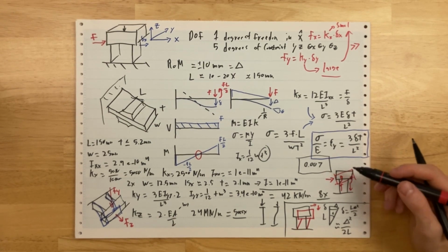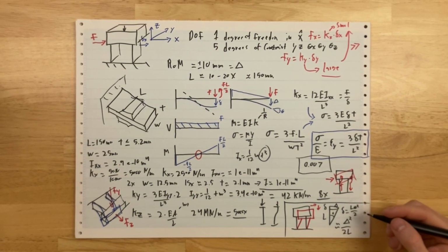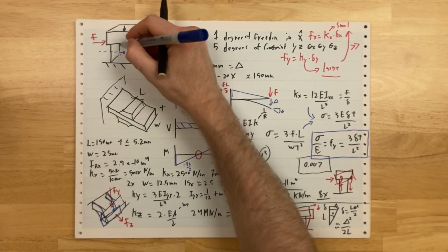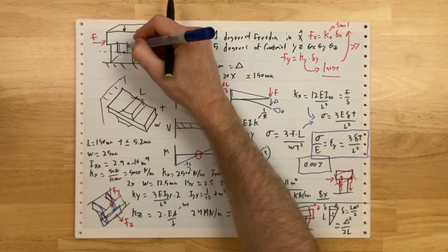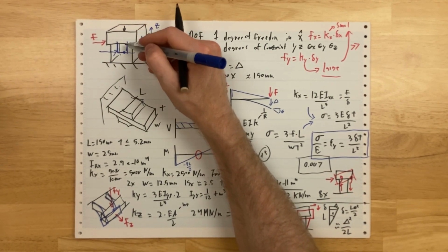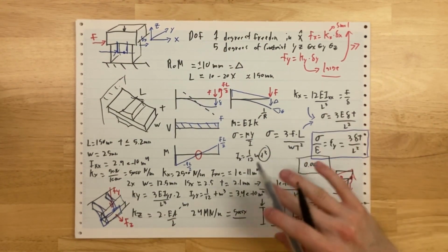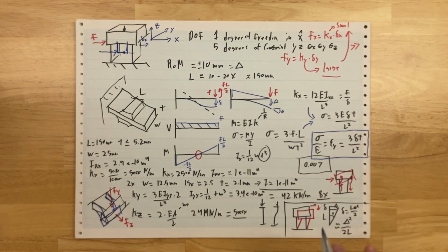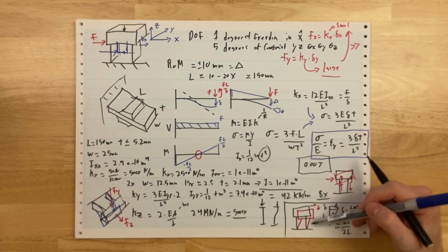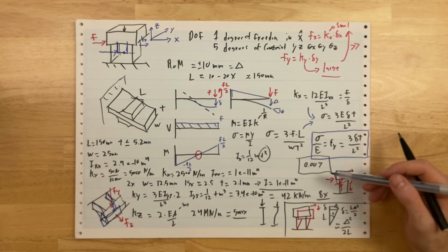If you work through the math, you'll find that the parasitic moment is FL/2. So what you can do there is if you push at the halfway point right here, let's say you build a bar that comes down from there, and you push at the halfway point, you can now add another torque that's FL/2 in the other direction. And that means that in static positioning, when you're moving really slowly, all the forces and torques balance out, you'll get a really nice pure motion with no tilting. So if you combine the double parallelogram to get rid of foreshortening, and you push in the center to get rid of this tilt, you can start to work out some of these parasitics.